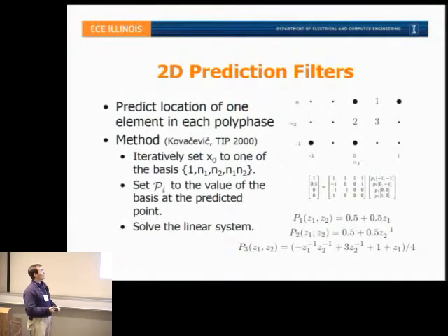So how do we set this up? To start with, we need to pick what angle filter we're going to design first. So looking at the picture in the upper right, I'm going to say, let's design an angle at 45 degrees. I'm going to pick 4 non-zero filter taps, and we're going to put them where the large black dots are.